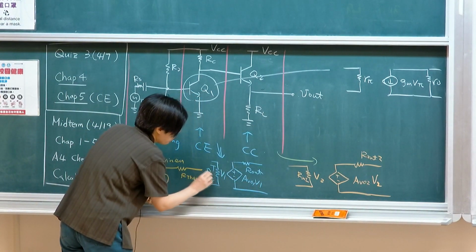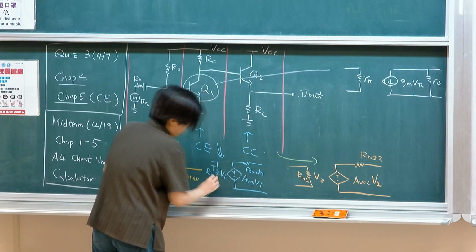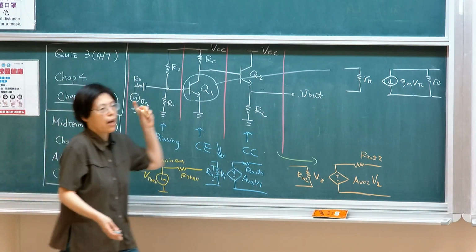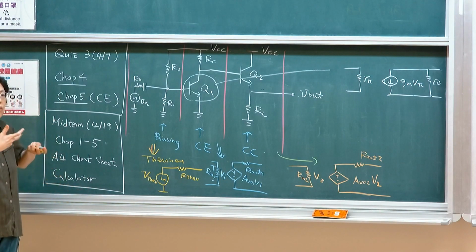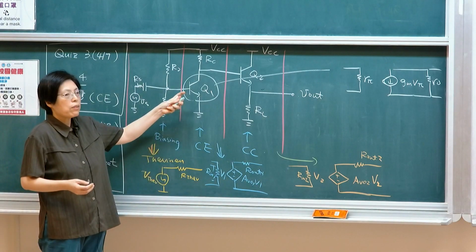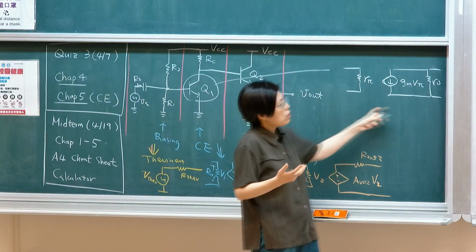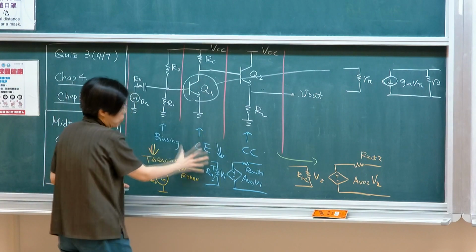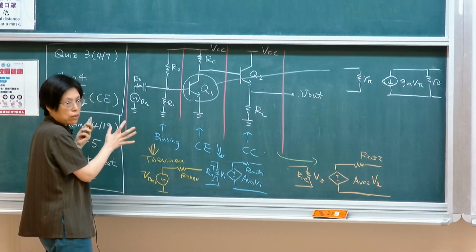You will then have 2 2-port models or multiple 2-port models. And then you link all of them together in order to get the input and output relationship of the overall system. So there's different levels of wrapping, as I said. We have a transistor, we all understand physics, and then we use this model to describe this. And then each stage, you generate a 2-port model in order to link multiple stages.